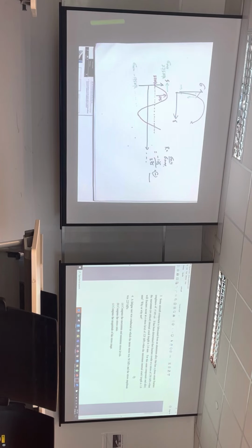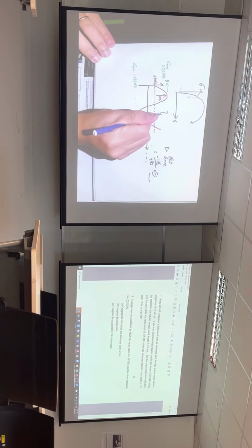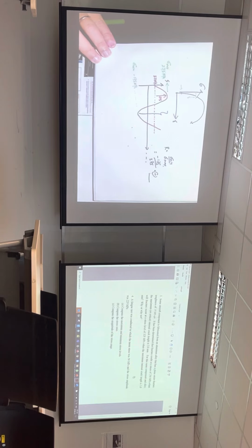If I just look at a few key parameters, I know what the stress is all about. And then compute the magnitude of stress range. Stress range, in very simplistic terms, is from this value to this value. You can take 275 minus this value, or you can just take 2 times 225, which is 450, because it goes up and down. So the stress range is 450. Does it make sense?